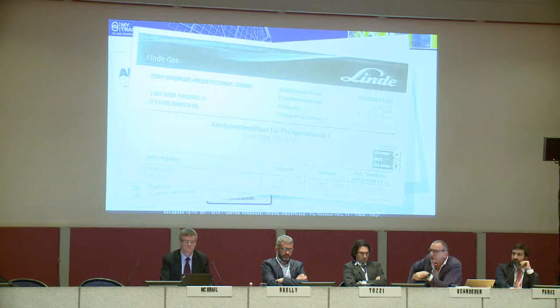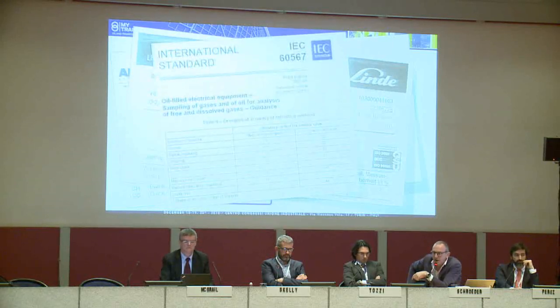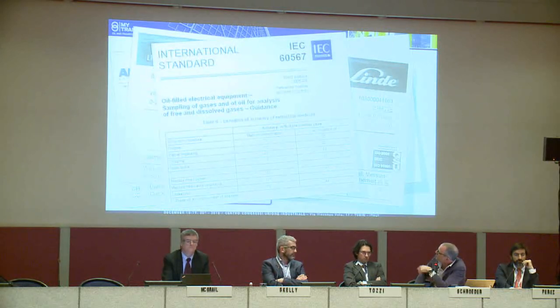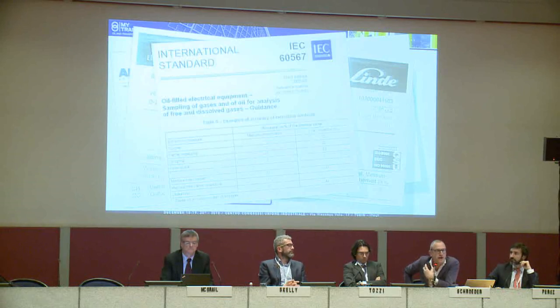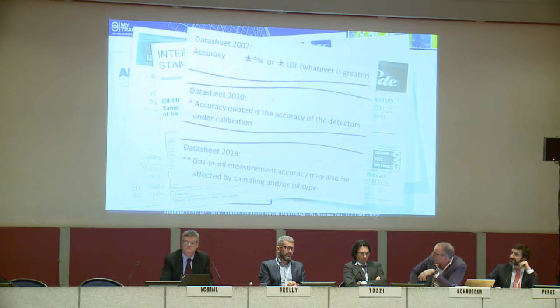And now the last slide, if you can just put it on, an excerpt from the very, very well-known IEC 60567, which compares different extraction methods with regard to the uncertainties. And here we see that especially the gas extraction is a major contributor to the uncertainty of an online DGA, and that no one has shown me the right solution for how to calibrate that really in the field. So if we can just move to the next slide. Yeah, that one you can skip.